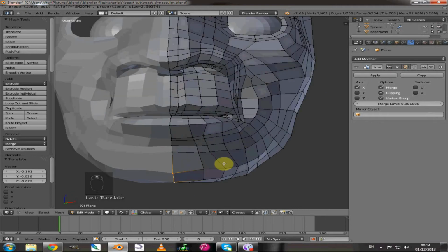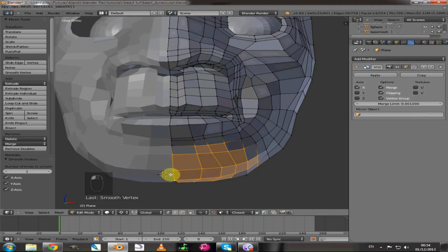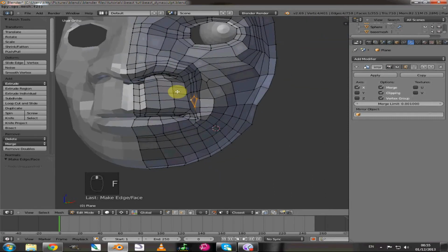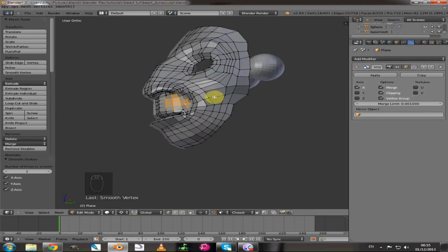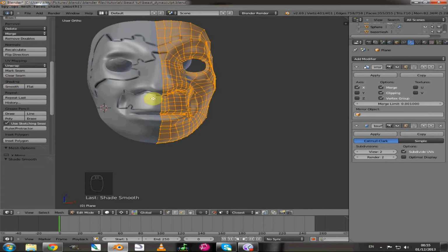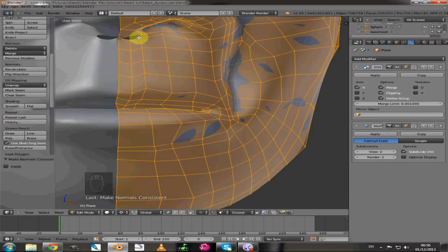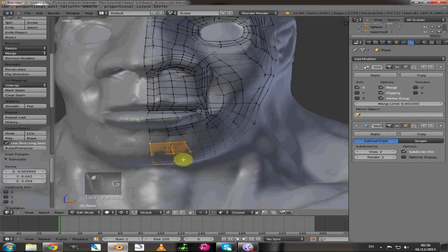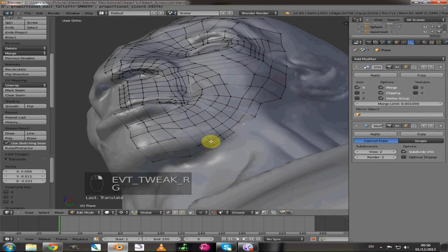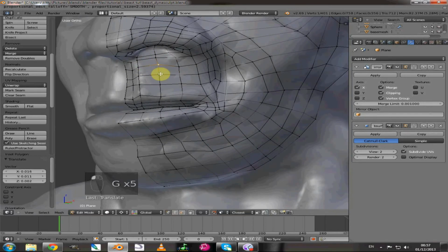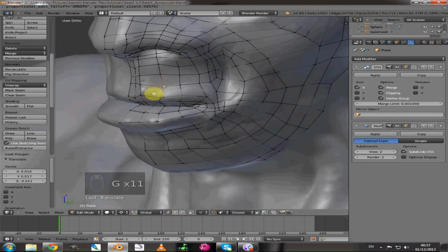and I'll pull the mirror in properly, and now I'm just smoothing out the vertices by pressing the W key and selecting the smooth option. And now I've put a subsurf modifier on and I've smoothed it and recalculated the normals. Now I can just come in and fill in these small gaps that have been left, and that's fine. Okay, now I'm just pulling everything back onto the base mesh, so it's all tidy and still fitting in with the contours of the model that we're working to.